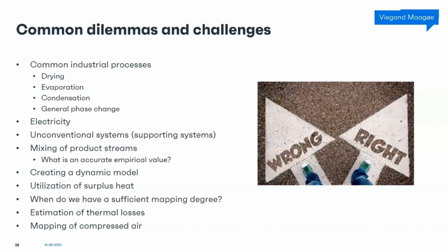However, when you are scouting, when you're doing your energy screening, you should evaluate your processes, whether they are using compressed air or not, because as explained earlier, compressed air is an extremely inefficient energy carrier.